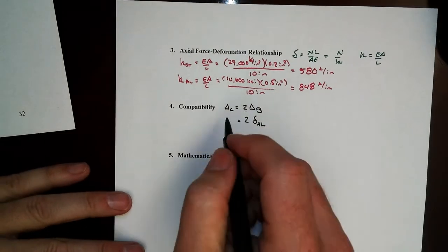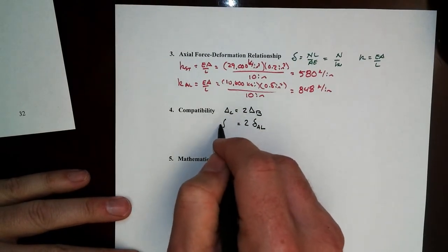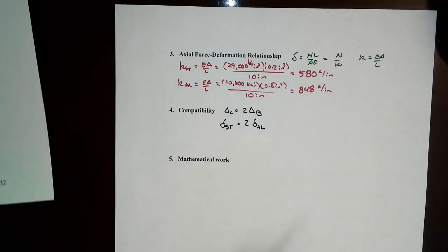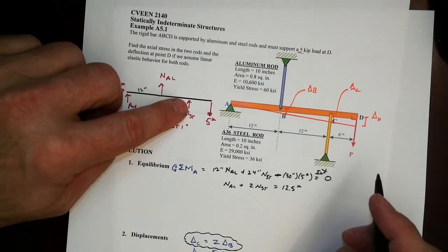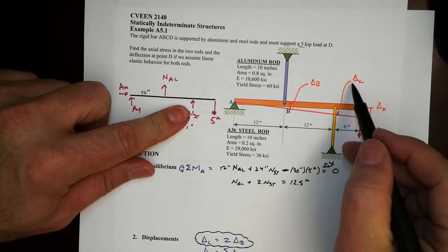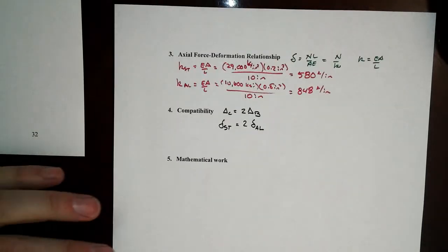In this case, it's fairly straightforward, and the same thing is going to be true over here at C, that if the steel is going to shorten, then it's in compression, and we've got that force already like that, and that's consistent with the positive delta C that we've got showing. So we've got to be very careful about how we're managing all that.